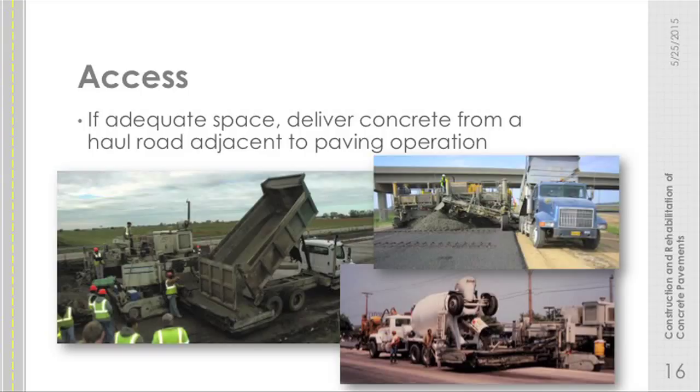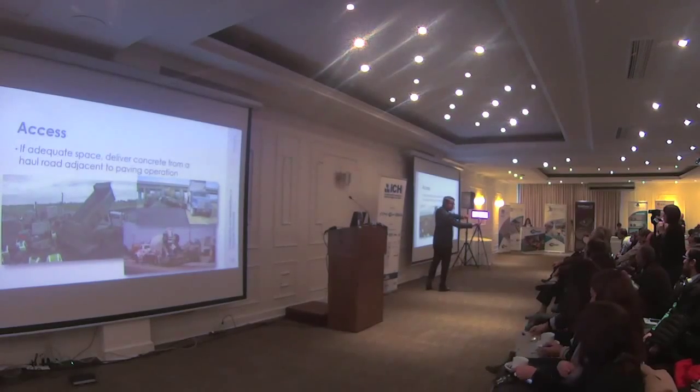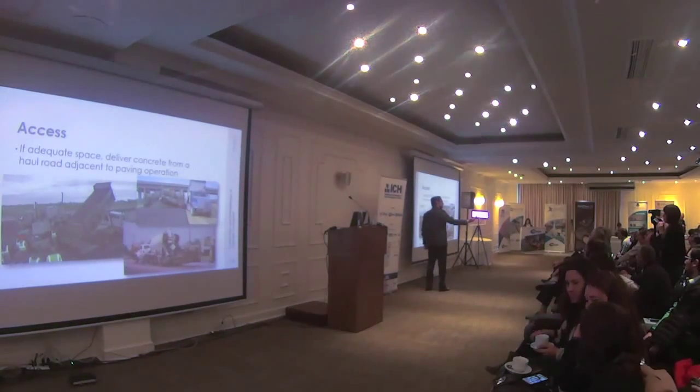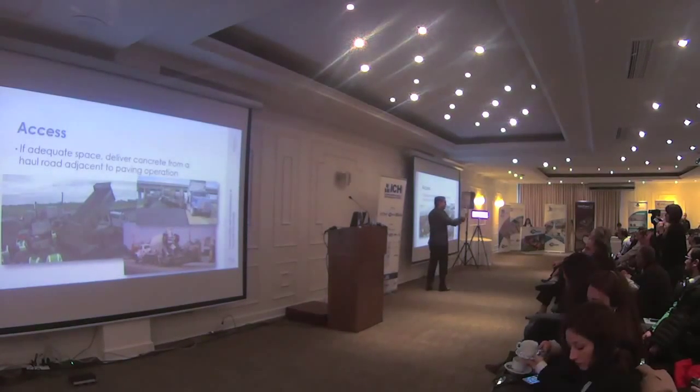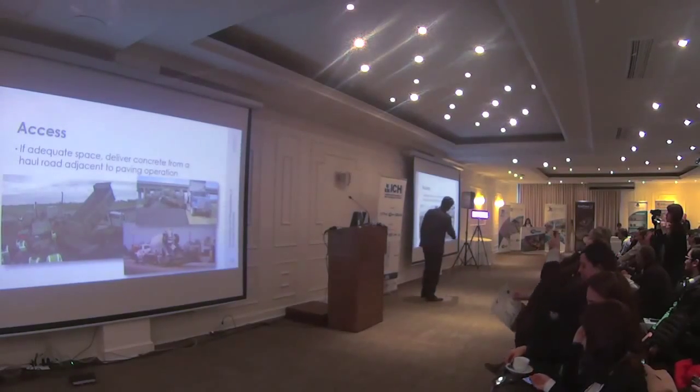The device in front of the equipment is called a placer spreader. It has an arm that just comes down. The truck dumps the concrete. There's a conveyor that then brings the concrete up into the paving. The arm lifts up, the next truck can drive up. Arm down, concrete, convey. So it's a process that just cycles.